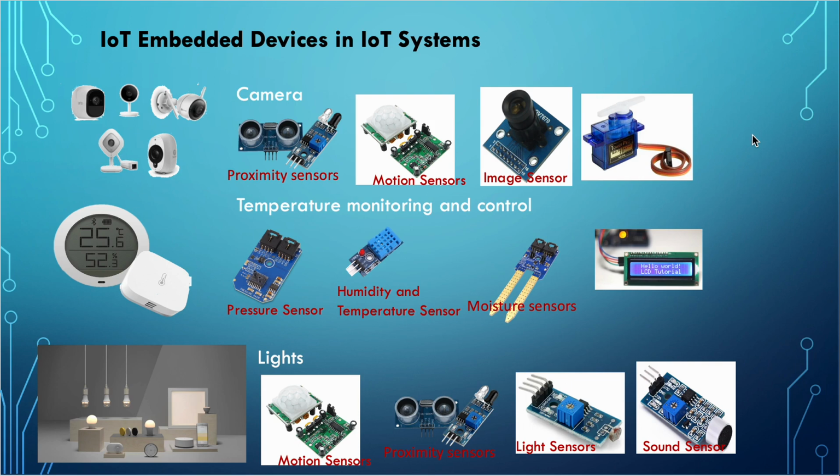When coming to networking, Zigbee or Z-Wave or protocols that are dedicated to IoT systems can most of the time not be used in camera systems, because the amount of data which has to be transferred is large, especially when you have HD images. But normal protocols for the internet, Wi-Fi, or Ethernet connections can be used for such applications.